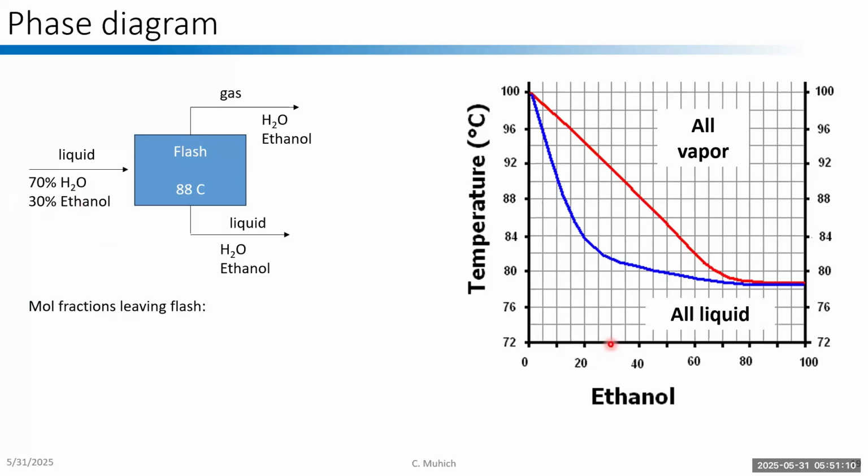That's this line. And I can say, okay, I'm operating on this point. I'm going to go all the way up to the temperature that I'm working at. And then I'm going to draw this, we can call it a tie line, right? So I'm working at this temperature. This is what's entering my stream. And then my stream is going to break into two components. My vapor phase is going to operate at this composition. My liquid phase is going to operate at this composition.